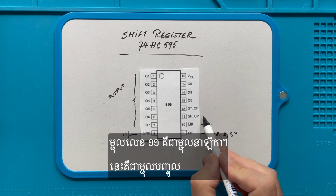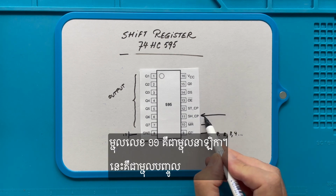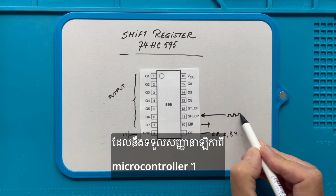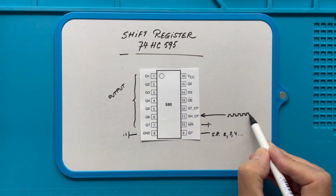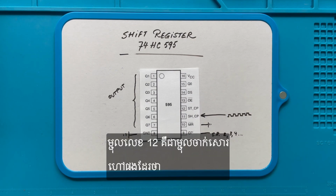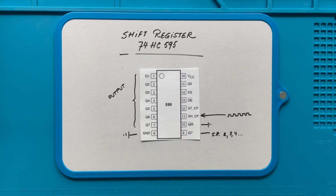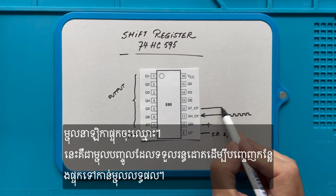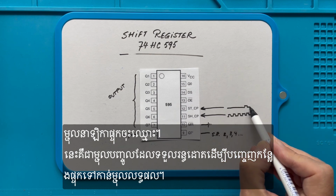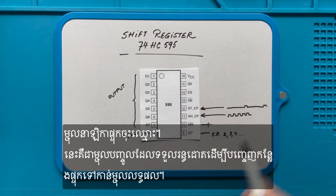Pin 11 is the clock pin. This is an input pin that will receive the clock signal from the microcontroller. Pin 12 is the latch pin, also called the register storage clock pin. This is also an input pin that receives the latch pulse to release the storage to the output pins.